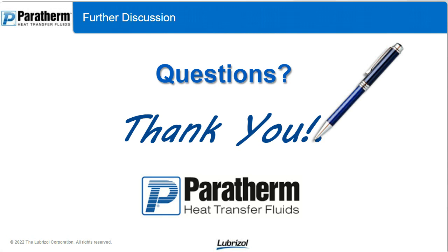Now, that being said, that's natural. Like I said on that one slide, degradation is going to happen over time. Color is usually a good initial indicator, but like you said, most thermal fluids over the initial year or two will turn darker. They'll get darker brown or even look somewhat black. It's a good initial indicator, but it's never going to be a condemning factor that the fluid turned dark. That soot buildup is just changing the color.